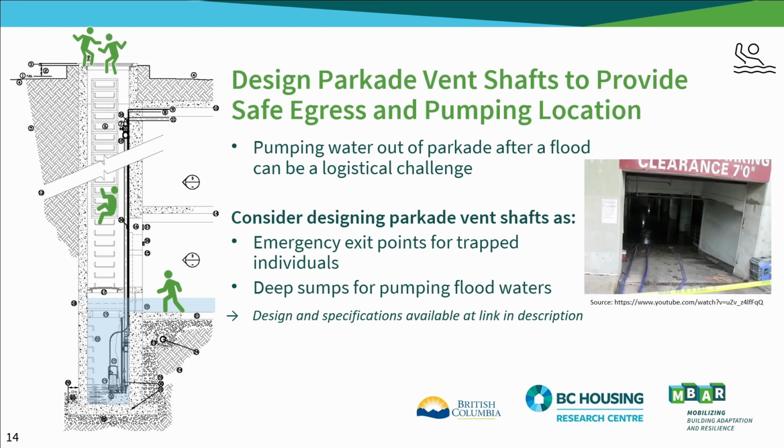After the 2013 Calgary floods, the sight of hoses winding up parkade ramps to pump out flooded parkades was common. To aid post-flood recovery, our vent shaft detail also includes a deep sump. Pumps can be directly lowered into this sump to facilitate dewatering, thereby increasing the efficient removal of floodwaters from underground parkades.